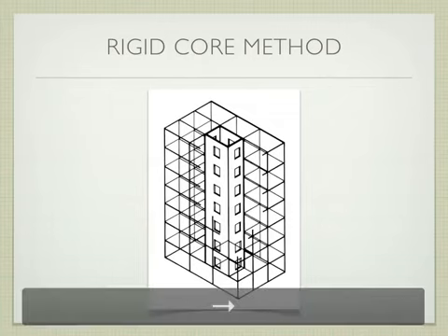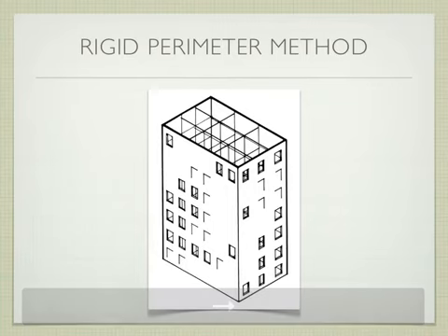The other option is to move all of those brace pieces outside. We can either put the shear wall on the outside, or we can put the diagonal braces on the outside, and we can leave the inside completely open. Obviously this building isn't a multi-story building, but we've elected in this particular building to have a completely open interior. We don't have a rigid core. Therefore, we have to have our lateral loading pieces on the outside walls. In this case, it's on this wall, not on that wall. This building was also built earlier than when they were really concerned about all the shear walls that are in it, but it's okay.